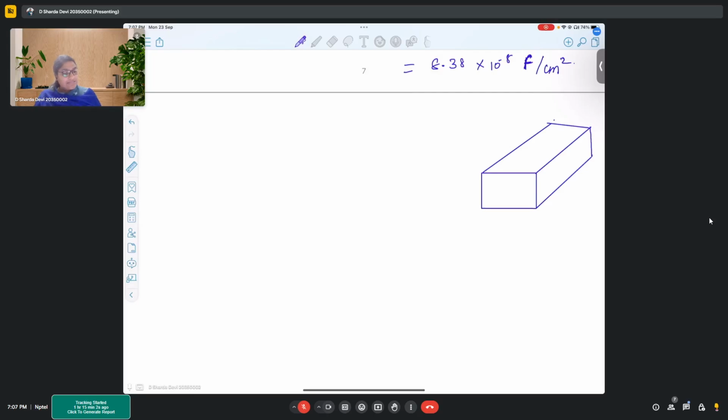So this is the junction that we will have. This is the drain side. So here we have the length of the drain side doping, the depth of the drain side doping, and this particular width is actually the width of the transistor. The total width is doped. So this is the complete width.